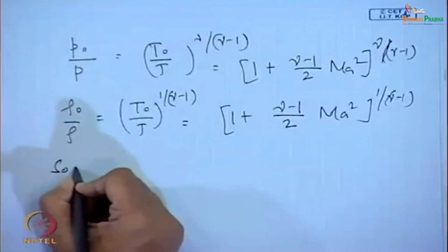Okay. So, therefore, it is not so very impossible. It is not that the stagnation properties are varying throughout the flow, and therefore finding them is of no use. For most of the cases we can assume isentropic conditions, and for that particular case the reservoir where the fluid is at rest, the properties of the fluid in that condition give you the stagnation properties. Agreed?